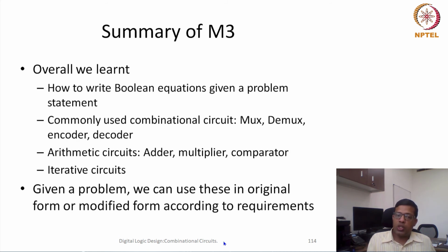A sequential process is usually slow, so we have found different techniques of doing things in parallel so that multiplication or addition could be faster. We have also seen there is an area and delay trade-off. If we try to optimize the delay, then area would usually increase, while the naive technique will have lesser area, but the delay is usually more. And in today's lecture we have seen iterative circuits, which is also a different approach to design a circuit.